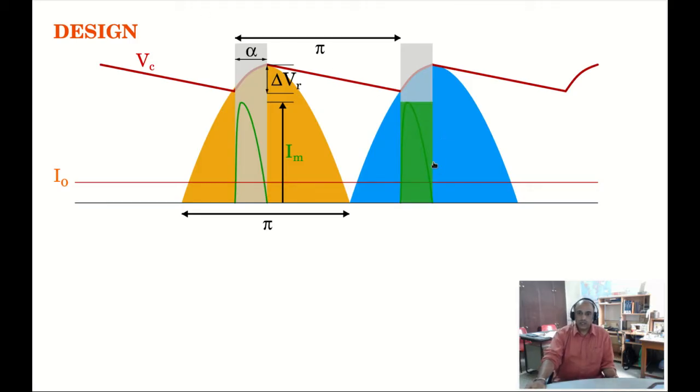You see, normally when we are rating or designing the components, there is not much to be gained by trying to calculate exactly the nature of this curve, because we need to give some safety factors anyway and we will normally be overrating the devices.